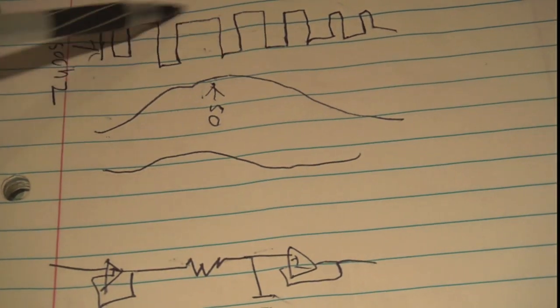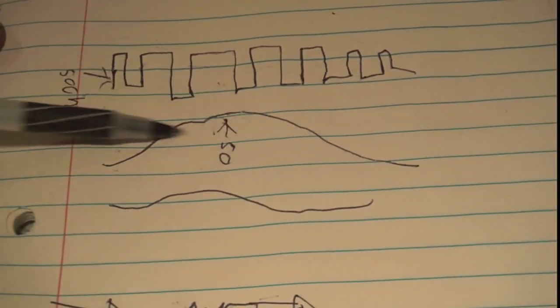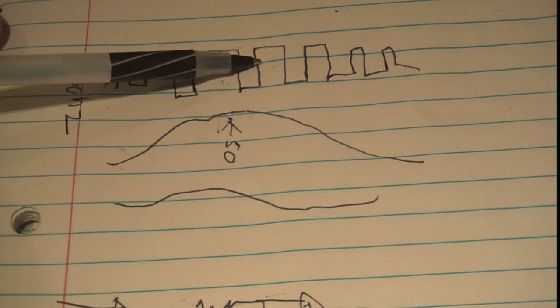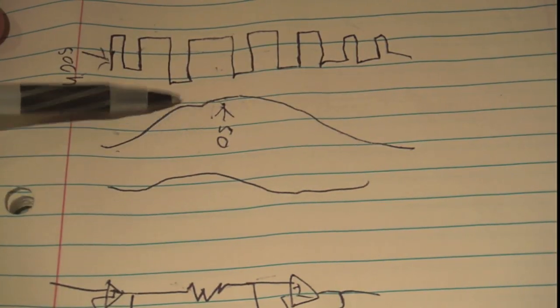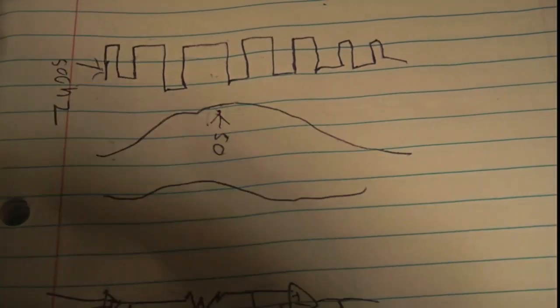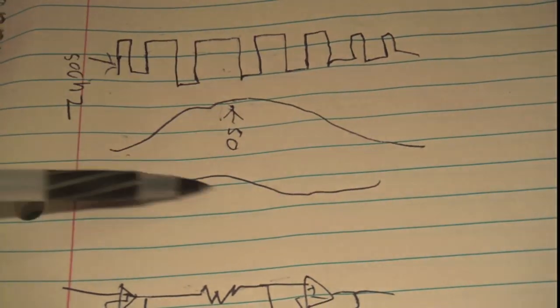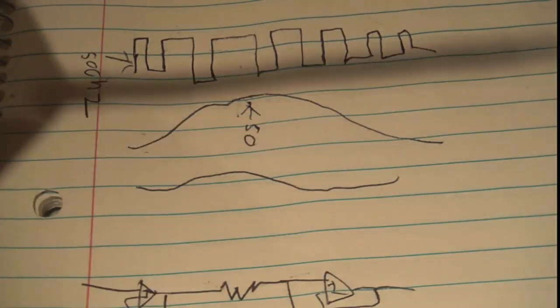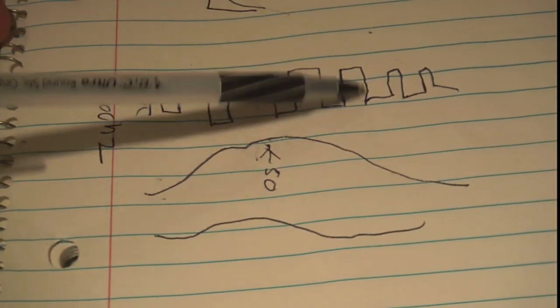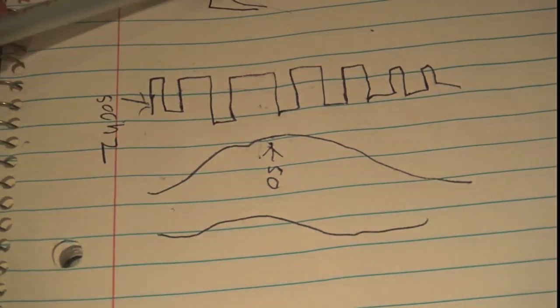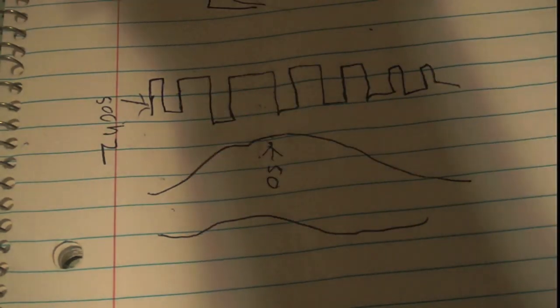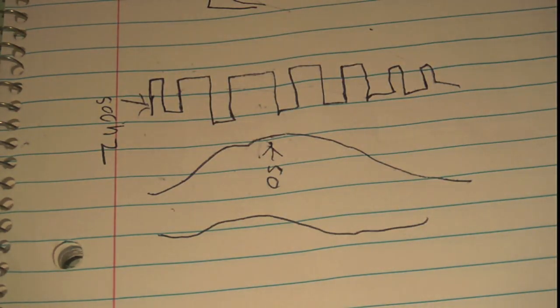So this frequency, we know we want this to be completely attenuated. We want this to be gone. The only thing we want left would be this thing. But we don't want this to be gone. So we have to realize what is the highest frequency signal that we want to be able to generate with our PWM. So not only do we want to be able to generate pure DC values at any one of the 255 steps in the PWM, right? But we also want to be able to generate some basic signals of some low frequencies.